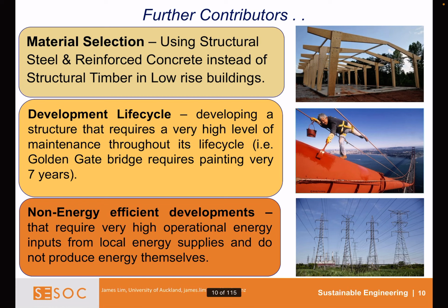Carrying on from the previous question, material science: for a standard project that requires structural framing, the use of structural steel and concrete could be replaced with sustainable structural timber or glulam. Development life cycle: developing a structure that requires a very high level of maintenance throughout its life cycle. A key example here would be the Golden Gate Bridge in San Francisco, which requires painting every 7 years to protect it from saltwater corrosion.